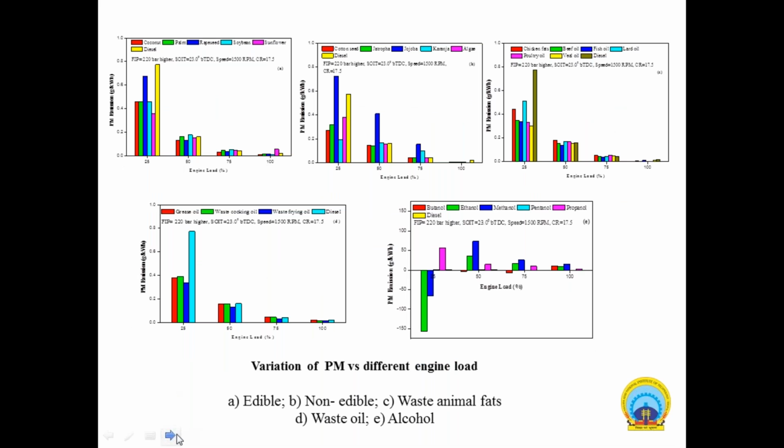There is PM emission with different engine loading. The PM emission shows a reduction in biodiesel and its blend with diesel fuel, which may be due to the higher percentage of oxygen content and better oxidation of air and fuel. The main factor of PM emission is improper fuel burning within the combustion chamber in the fuel rich section.